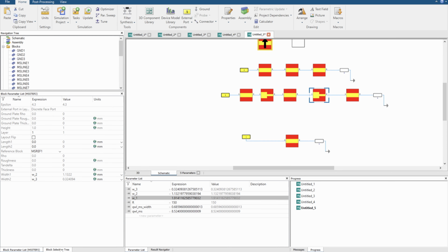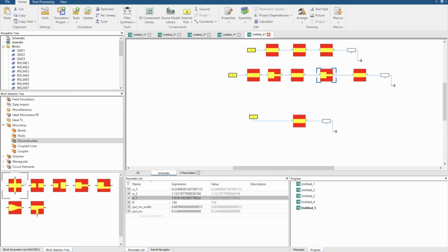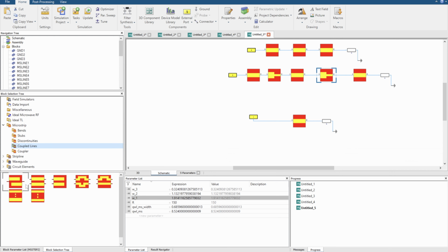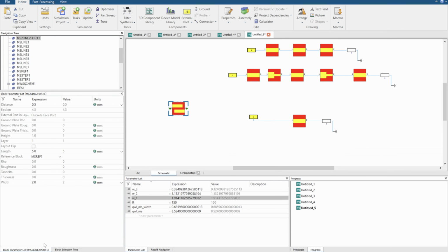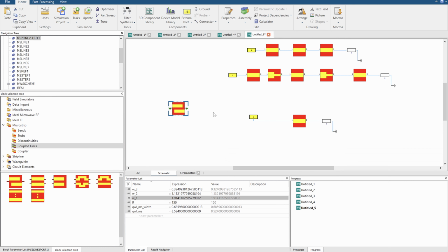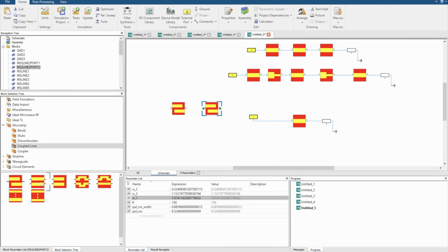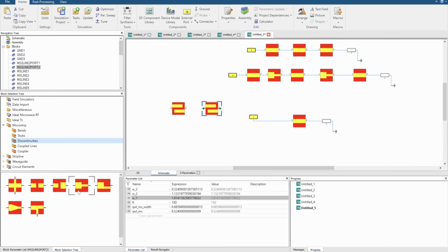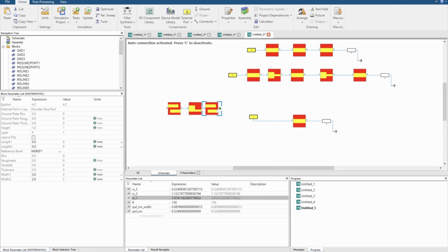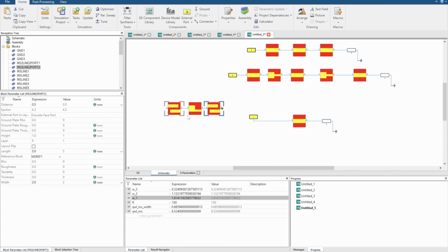Okay, and the same goes if you want to use a coupled line, for example here, a coupled line to another coupled line which had a different kind of length to it, or different, sorry, thickness or width, you would then need to add a similar block, or you can add one of these steps to it, and that will account for the shift in width and so forth. And you can create hairpin networks, you can create coupled line filtering networks and so forth.